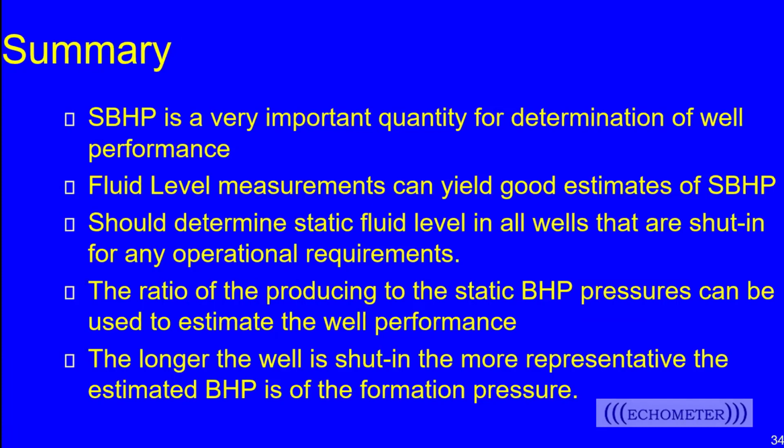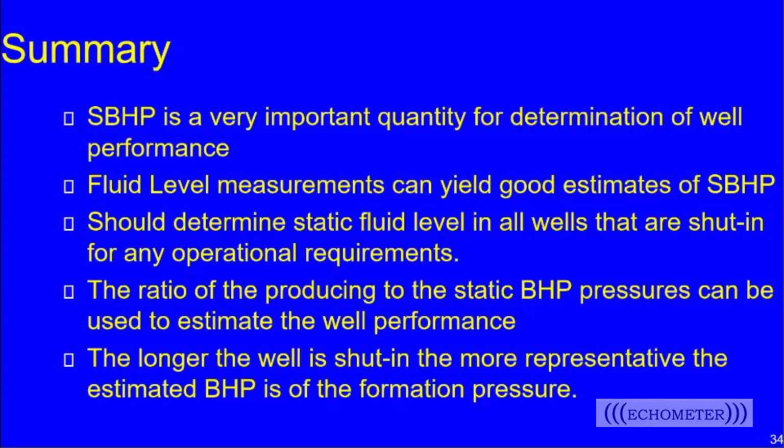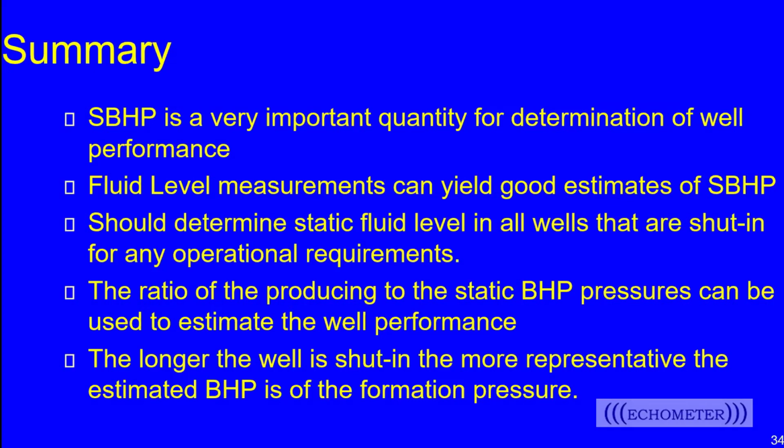Well, I hope that you found today useful, and you found that the static bottom hole pressure is a really important part of determining the well performance. It's a piece of information we need to solve the puzzle. And we can get fairly good estimates of the static bottom hole pressure off of the fluid level measurements. And while we have the chance, we should get this on all the wells that are shut in for any operational reason. So the more static bottom hole pressure information we have, the better off we are. We'll see variations between the field, depletion changes throughout the field, and so on. And then having that and the producing bottom hole pressure, we can determine the well's performance. And the longer the well's shut in, the more representative we'll get of the reservoir pressure.